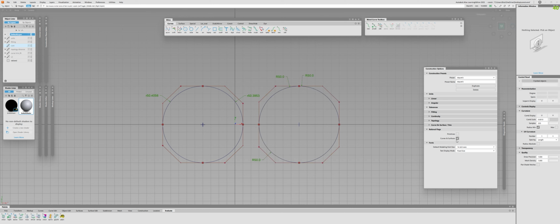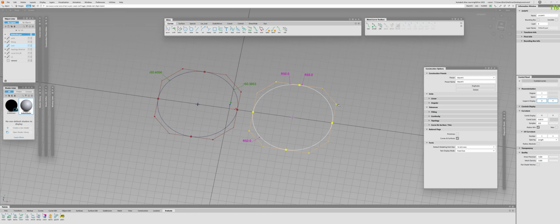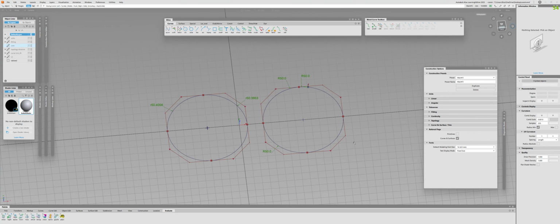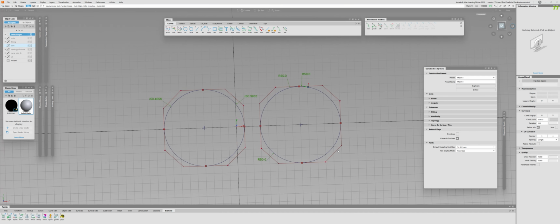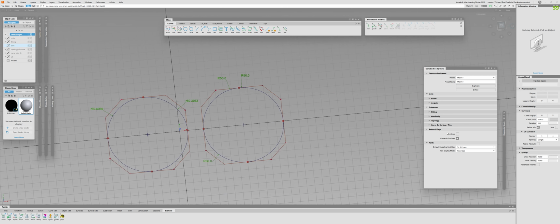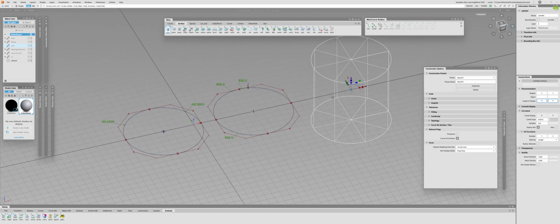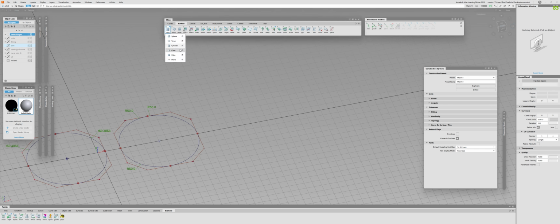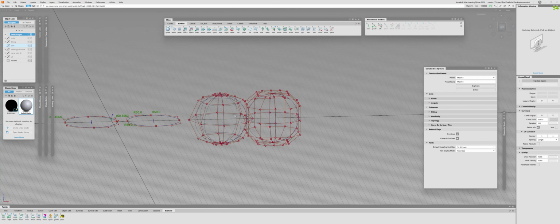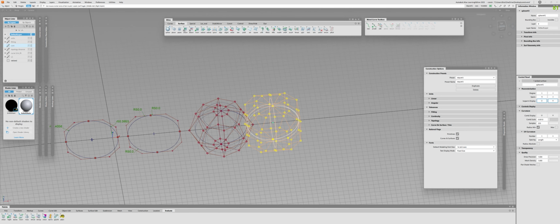Now, as you can see, there are two checkboxes, one for primitives, one for curves and surfaces. It says and surfaces because you can create revolves or profiles from these rational curves, and they will have this rationality with them as well. The primitives option is very simple, just primitives. Primitives are spheres and cylinders. So let me quickly illustrate. So this is the cylinder. And, oh, sorry, let me go to an example with the sphere. So this is the sphere without the rational flags, and this is the sphere with the rational flags. As you can see, they're different. This one will be perfect, this one will not.